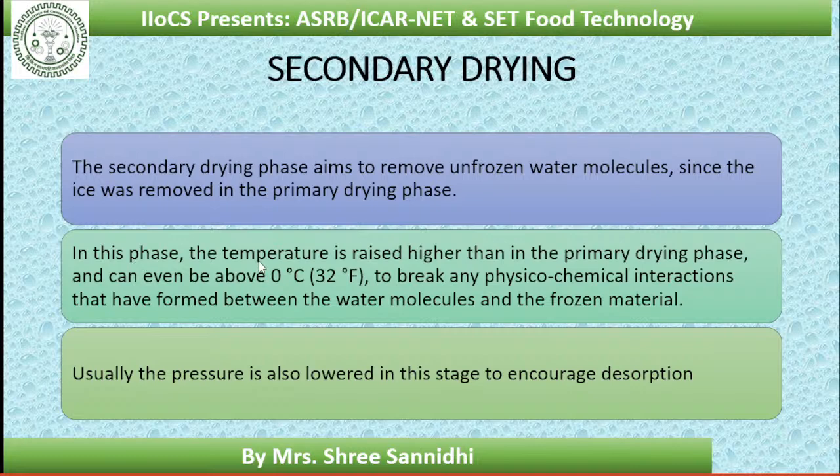In this phase, the temperature is slightly raised compared to the primary drying phase and can even be above 0 degrees Celsius to break any physico-chemical interactions that have formed between the water molecules and frozen material.